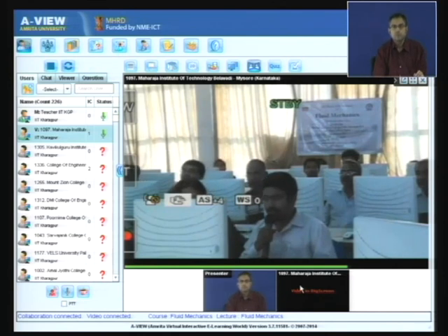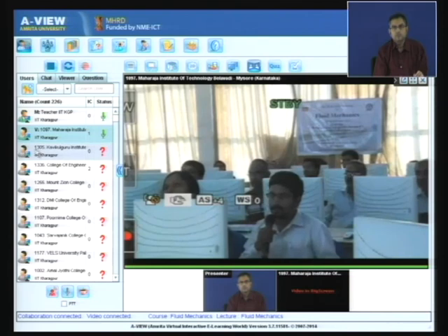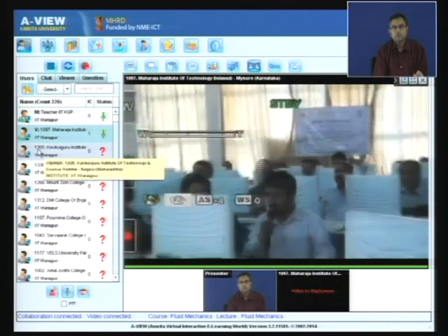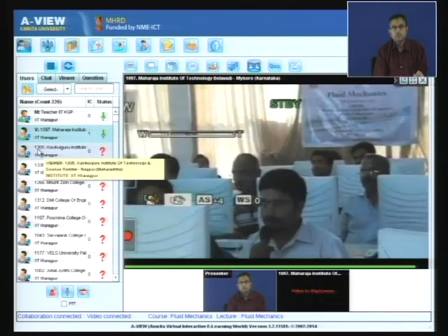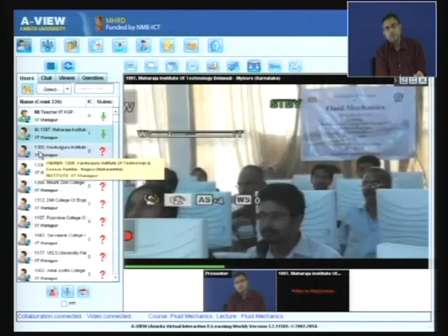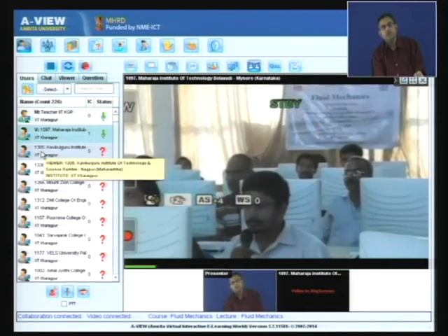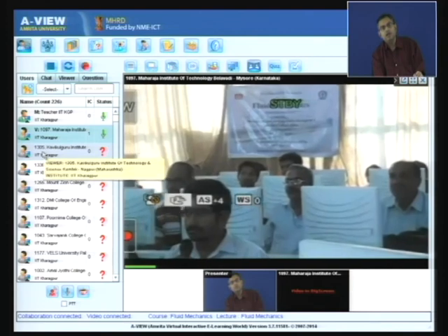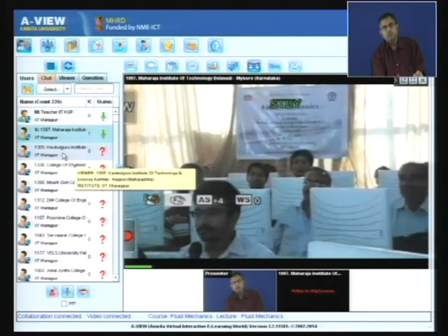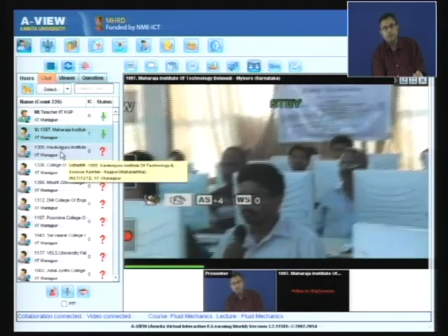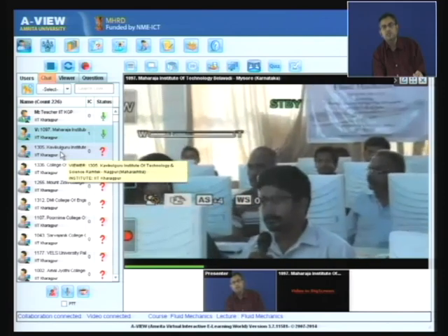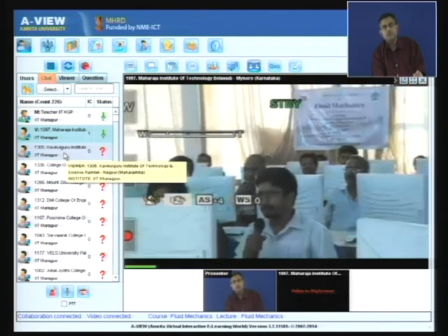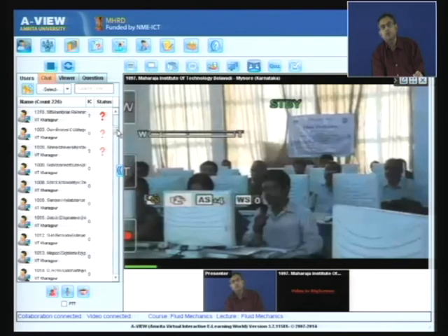The question is about external flow. Can we apply the similar analysis which we did for flat plate to a flow over an aerofoil? Yes, just the geometry will be different. Instead of a flat plate it will be a curved surface. Similar considerations can be applied, but you have to be careful about the flow separation, because if boundary layer separation occurs you can no more use the boundary layer theory.